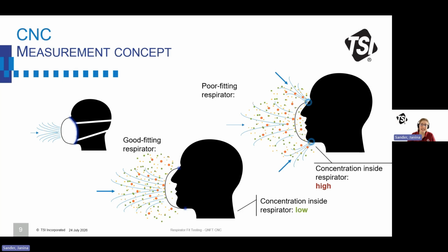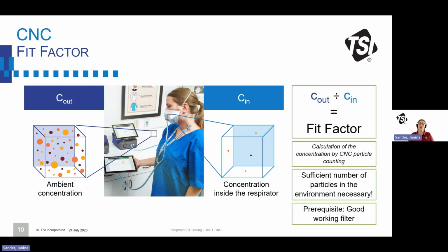This leads us directly to the value we are using to evaluate the fit, which is the fit factor. The fit factor is the ratio between the outside concentration, the ambient concentration, and the inside concentration, the concentration inside the respirator.